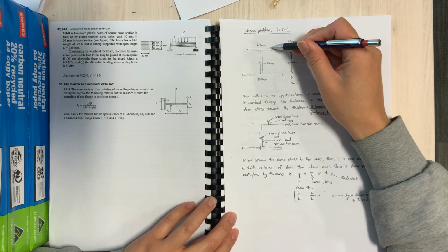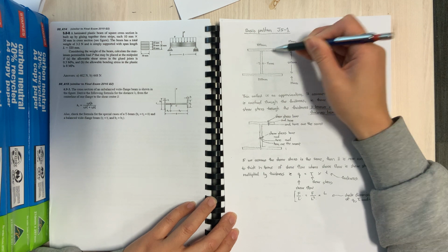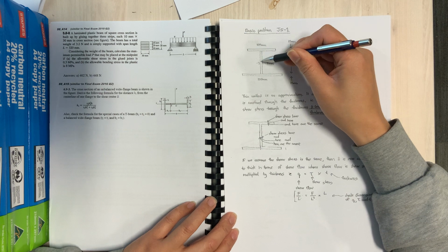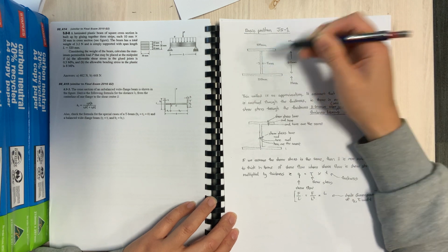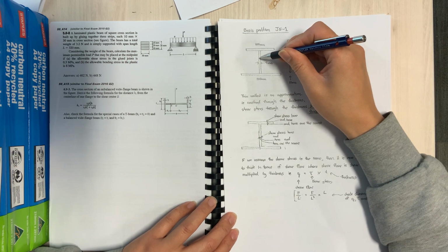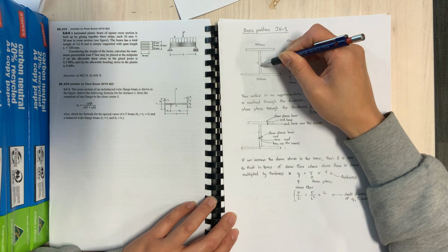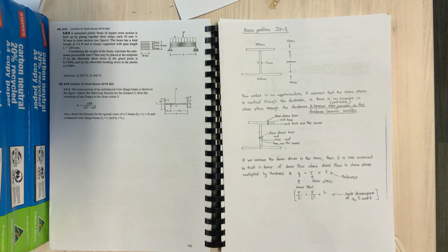You're saying that there's no vertical shear being carried by the horizontal members, and all the vertical shear is being carried here, and you're saying there's no variation of shear stress along here. So everything effectively has been packed going down these center lines. So it is an approximation.